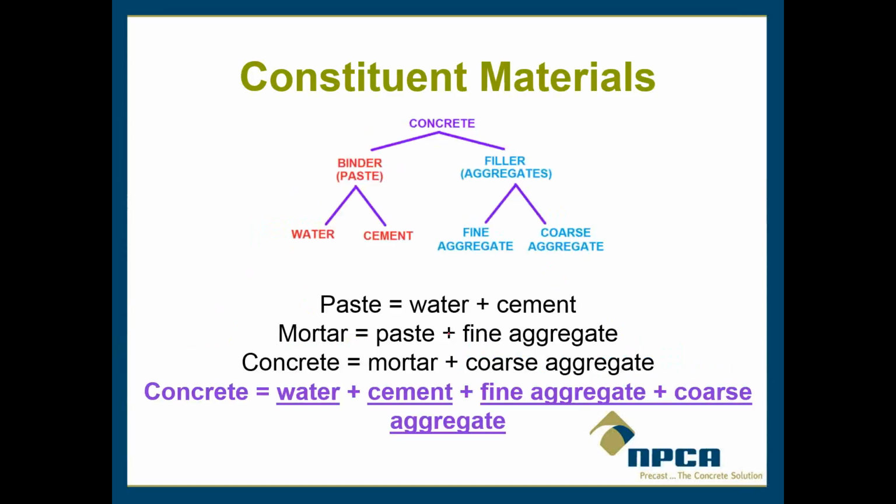And just a little clarification, paste is the water and the cement. Mortar is different than concrete. Mortar is not paste, mortar is not concrete. Mortar is paste and fine aggregate. So mortar is water, cement, and fine aggregate such as sand.